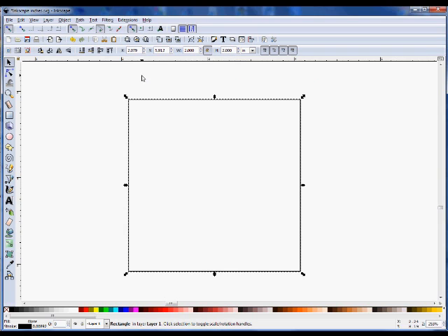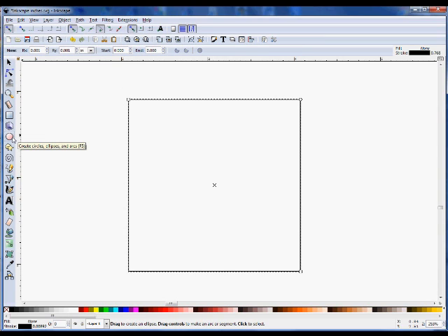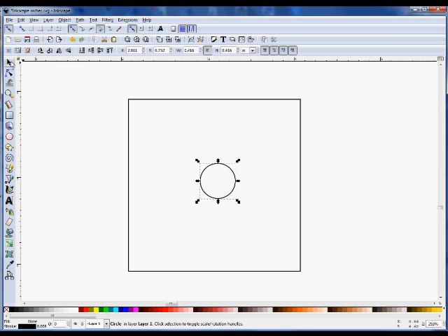So now it is set, and let's say you wanted to drill a hole in the center of it. You would grab the circle tool, hold down the shift key and drag it down, and again you click on it so that it has these arrows. Click on this select key. Again, this is still locked, so whatever size you want. Let's say you wanted a 1/2 inch hole there. So you click it on 1/2 inch and it's going to be a 1/2 inch hole.